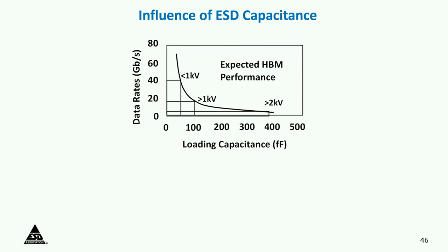So now you are trying to deal with such high current with a microprocessor built with very thin gate oxides, which break down under ESD regime at something like 4 to 5 volts. Imagine that. Now you're trying to build something that will clamp to 4 volts. Any little resistance in the bus can actually increase the voltage. So the diode has to be so small, and that means you cannot reach the levels that you're trying to reach. So that's the reason there is a whole revised thinking: I should be designing for current, I can't be designing for voltage. It's the current that makes any circuit application limited. How much current can I handle?